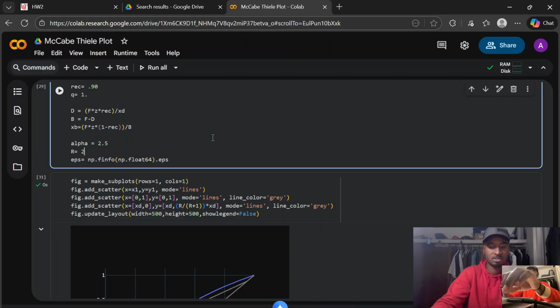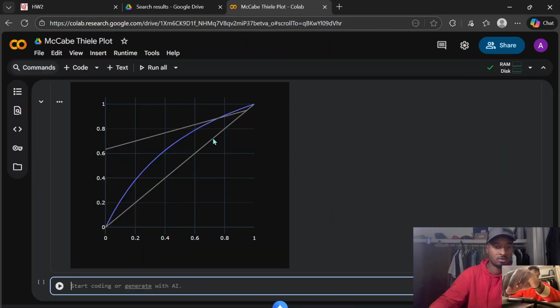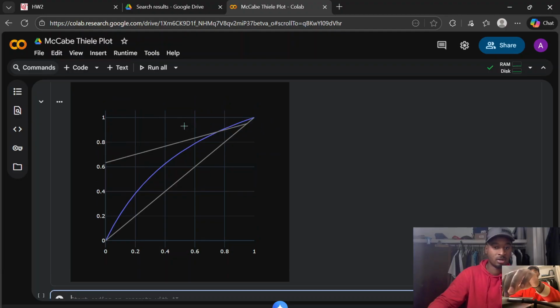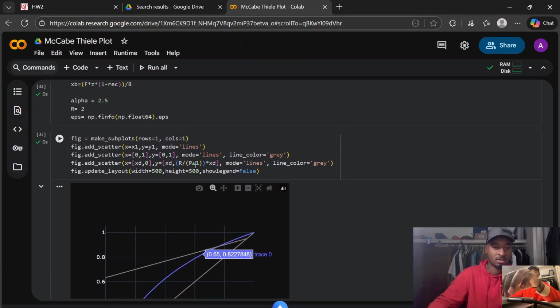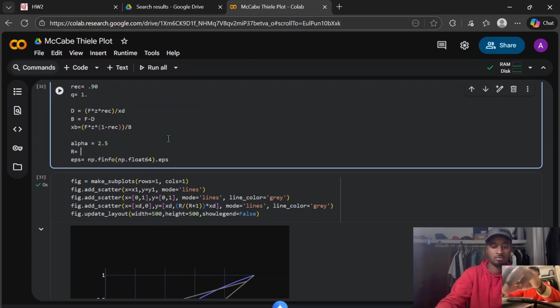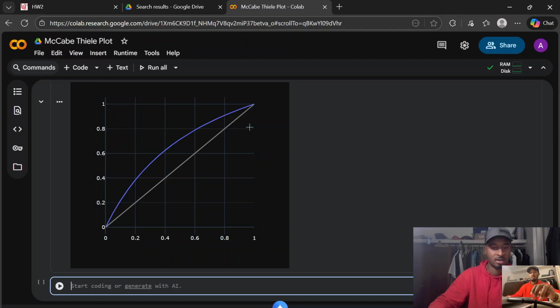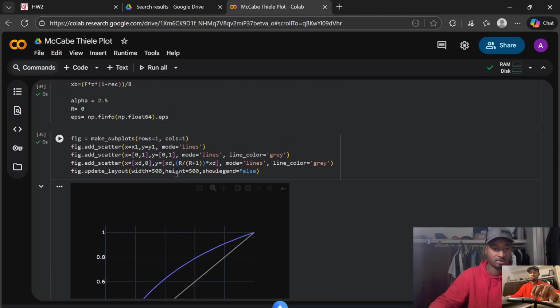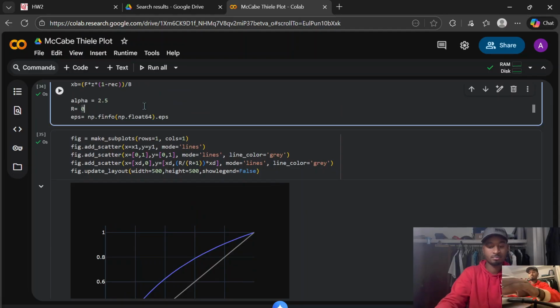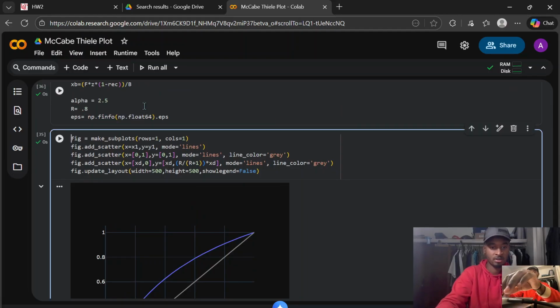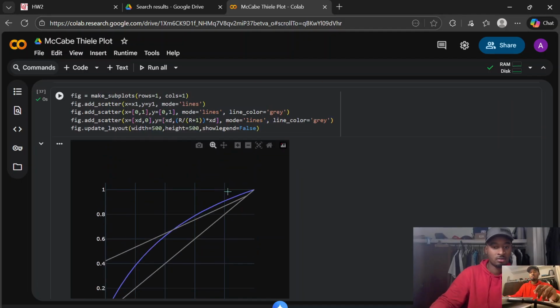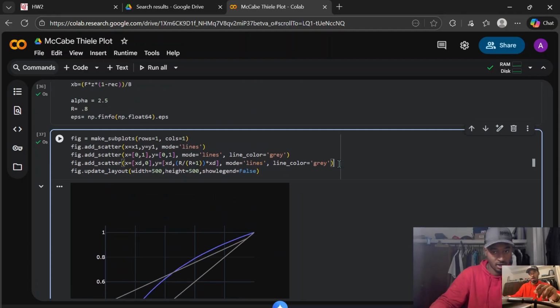So here we have our rectifying line here, as shown, and we can adjust this by messing with the reflux ratio, and we see how far off it deviates from this y equals x line here. So if we even put that as 0, it follows the y equals x line right there. So that's our rectifying line. Now let's model in our Q line.